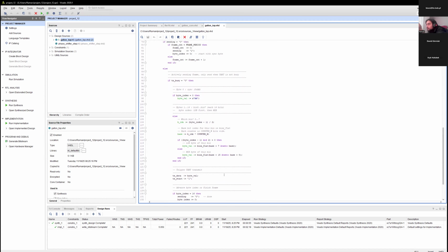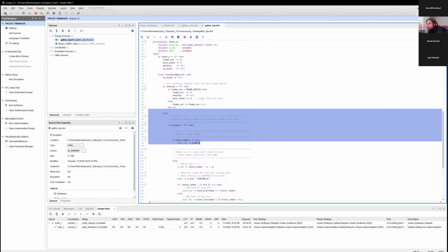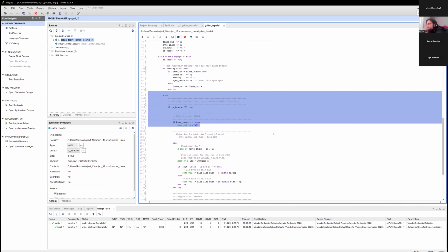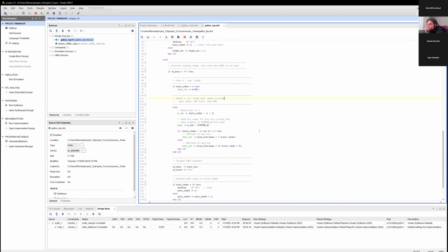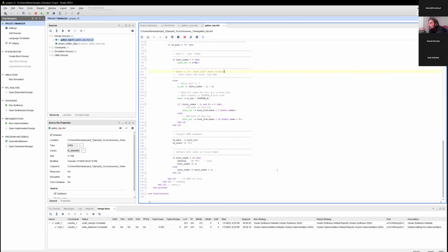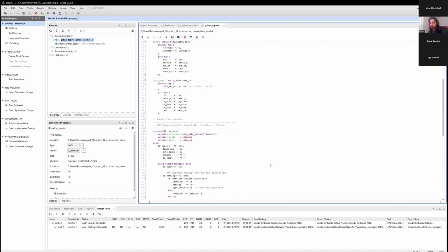It's checking to see if the UART is busy or not, indexing the bytes and putting the data in particular bins as we've defined it, and sending all of that through a port in our device. So it basically goes into this particular FPGA.